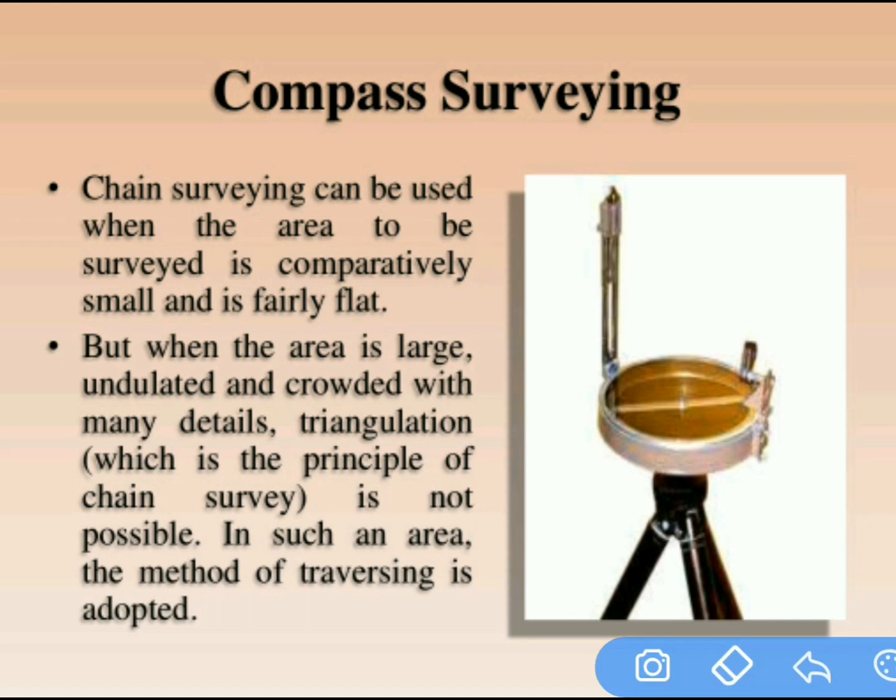But for example, if the area is large, then we cannot use a chain. Yes or no? Yes. If the area is undulated, meaning ups and downs, then also chain surveying is not suitable.